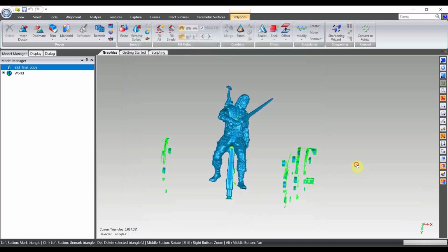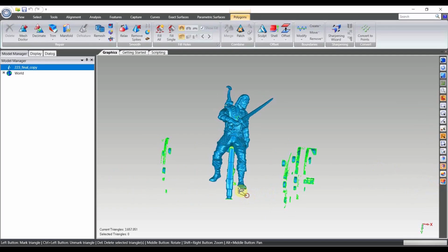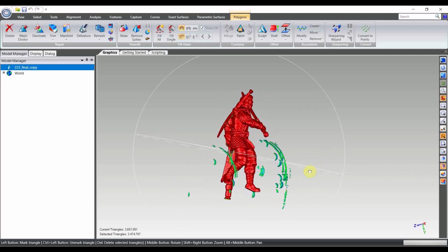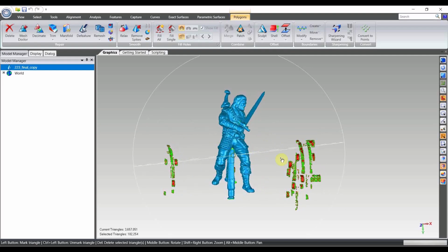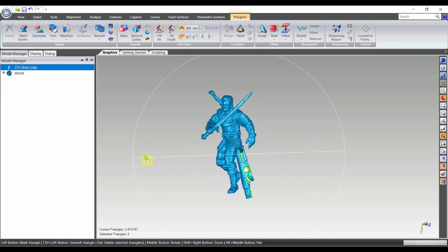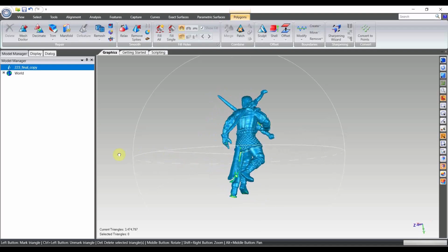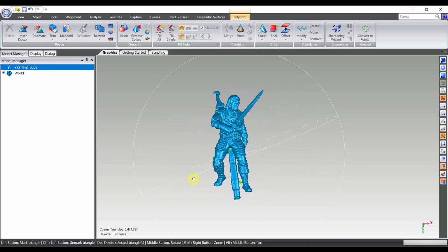In the software main window, from the right toolbar, make sure that the Select Through and the Select by Angle mode are enabled. Then, it is enough to select any small portion of the main object, so the selection will be expanded to all contiguous meshes automatically. In the next step, we inverse the selection to select all isolated polygons. Then by pressing Delete button on the keyboard, all isolated polygons are removed and only the main object remains.